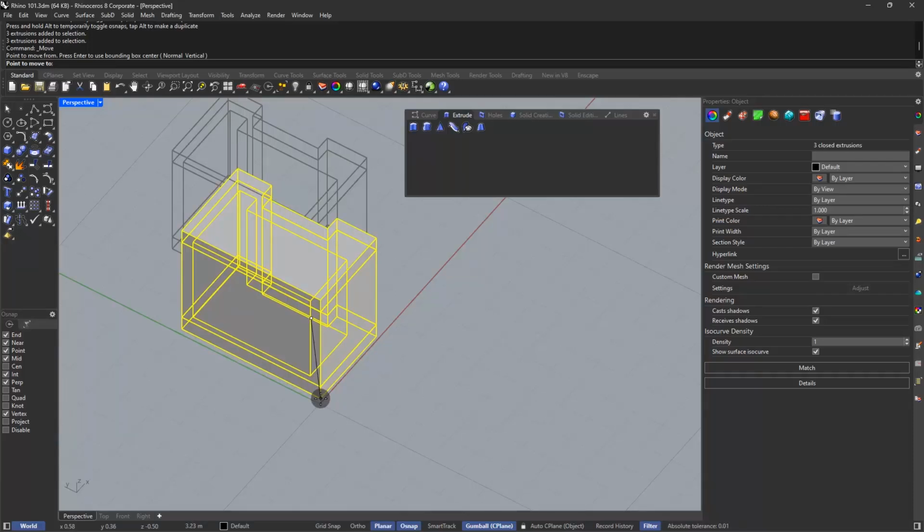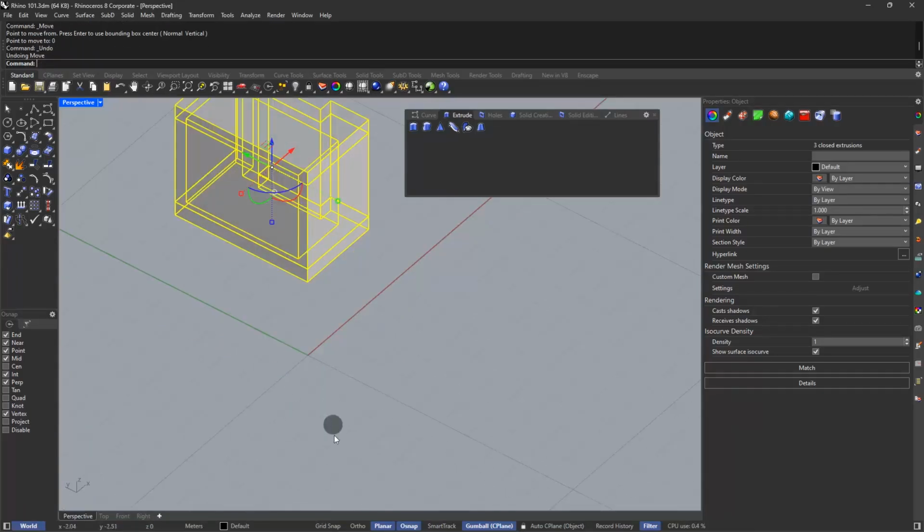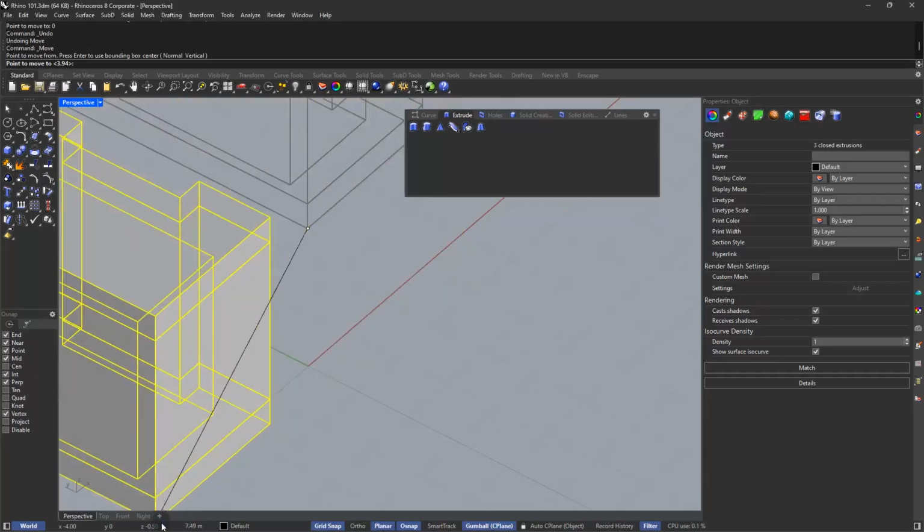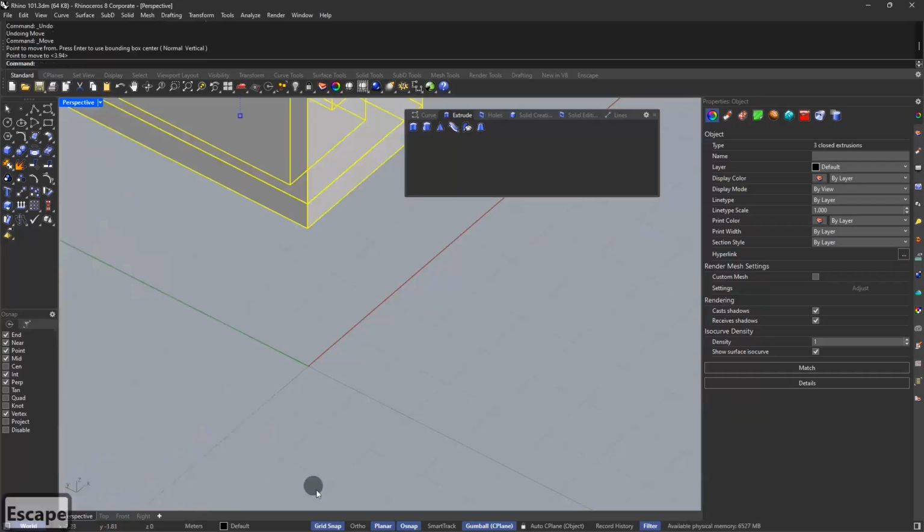So you can do it using multiple ways. For example, you can type 0 and tap enter is the first way. And you can activate your grid snap option here. So if I use move command, as you see, we have a snap. But our z coordinates is minus 0.5, so we don't use this method here. I will disable this again. I usually don't use grid snap option.